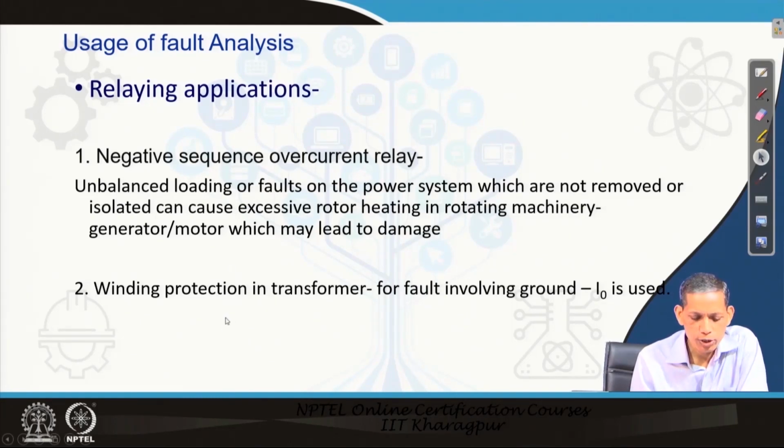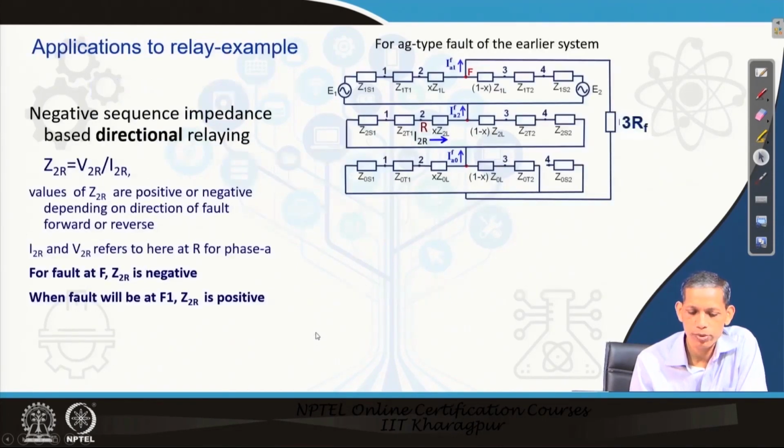For transformer protection, for faults involving ground, the zero sequence component will be available, and for many winding protections of the transformer, the zero sequence component is used.